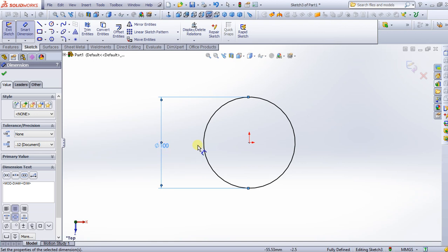Why is it 100 millimeters? Now if you open your SolidWorks, you must endeavor to select the units you are working with. Come to this task bar, you select this unit palette. Click on the flyout to give access to different units.